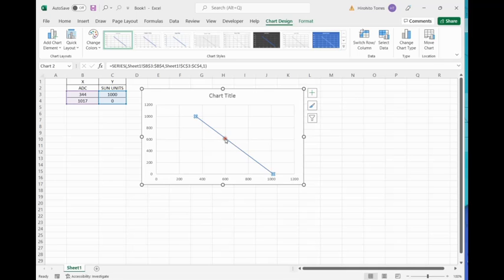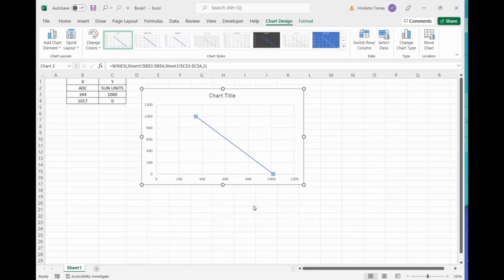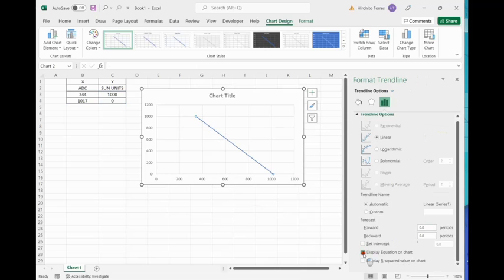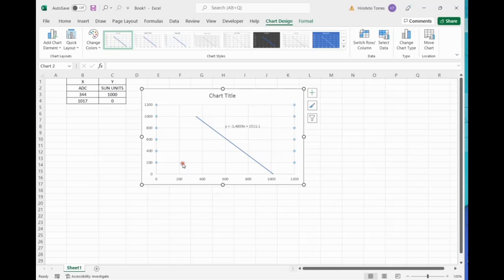So now what I should do is select the trendline, so that it gives me the nice equation that I need, and that's it. So now I got the right equation. With that equation in mind, I can convert any ADC value to some value, and it will make more sense to me instead of reading ADC, which doesn't make any sense.